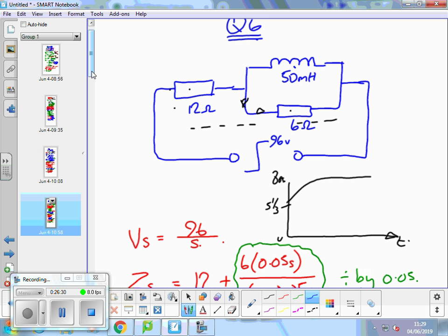So you're using what you know in a maths lesson. This is electrical principles. You're using what you know about those circuit components to think what we are expecting to happen here. We've already covered what happens with just an inductor and a resistor in series. We knew that was exponential rise. Now we've added that to a parallel circuit, so we're going to start off with some current, but still get exponential rise to a limit. With an inductor, that's what you're going to see.